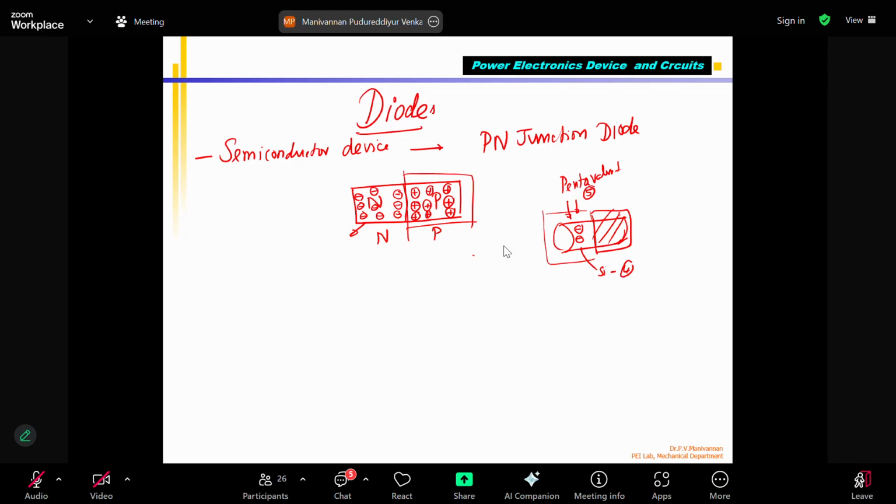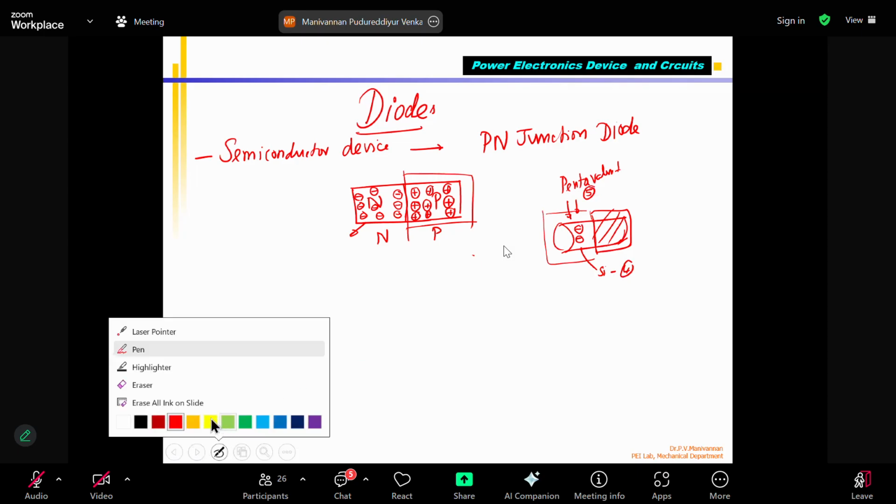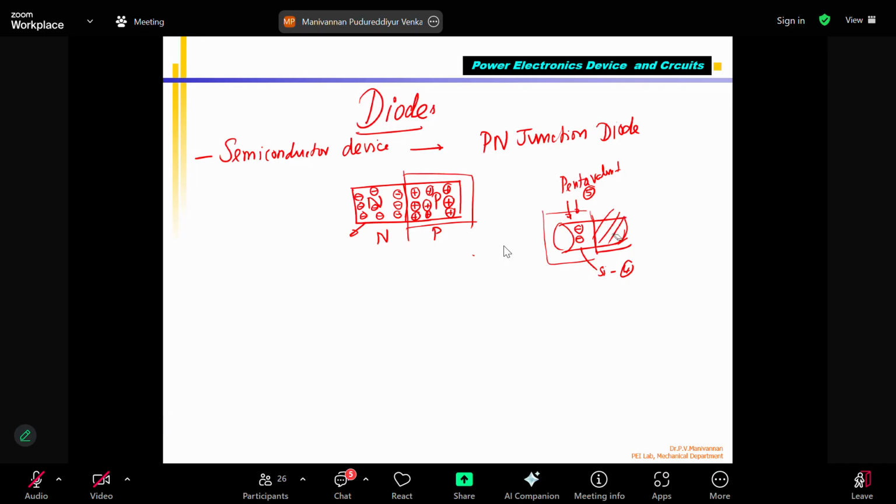Close this part, and then you heat the other half. You heat the other half, then aluminum in vaporized condition, atoms will come in. The whole thing will be in an enclosure, almost a vacuum, an ultra low vacuum. No other material should be there. Sometimes they flush it out with argon, all those things, clean it out, then create a vacuum. Nothing else, even argon should not be there. Everything will be removed inside a vacuum chamber.